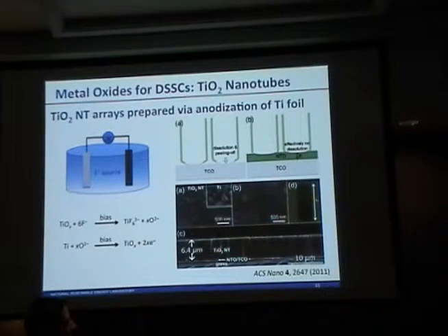What happens is you have dissolution of your titanium hexafluoride anion, which is produced there under these bias conditions, and then you have further reaction of titanium metal that's then exposed by that dissolution to make your titanium oxide. And the titania, I show as TiOx. You do need to anneal it to get crystalline anatase. If you anneal it too long, you get rutile.